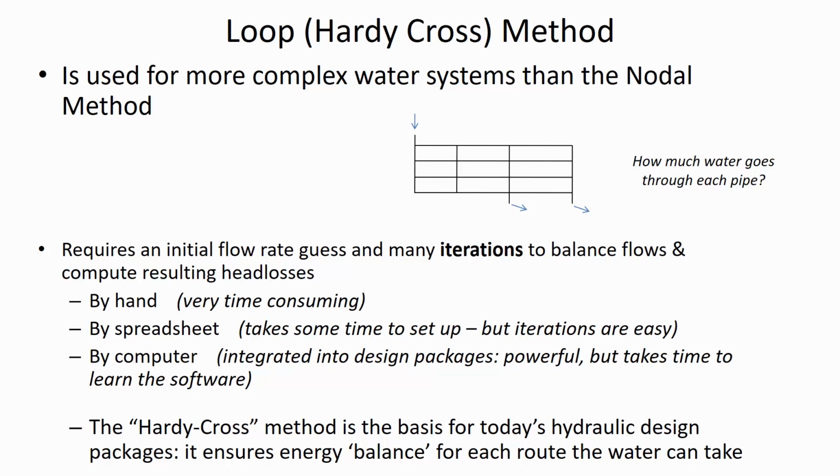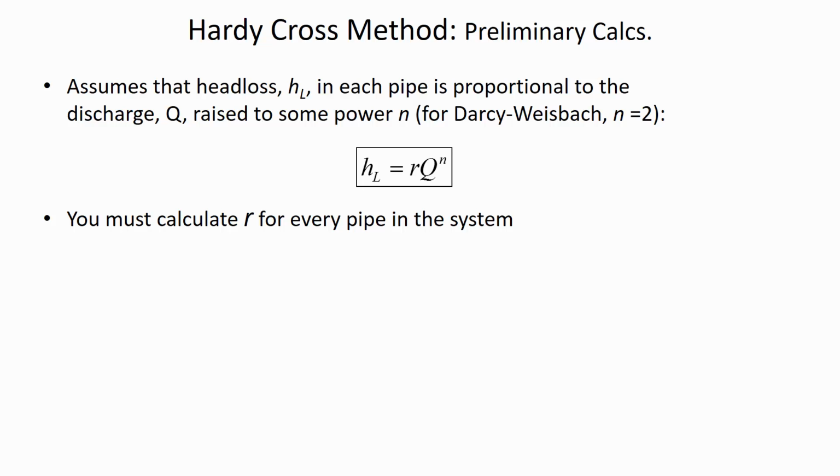You know, if you have a really bad guess of flow rate, then that would throw off your value of f. But for now, let's just say that if we have a reasonable estimation of f, let's say maybe we applied the fully turbulent flow assumption, then in that case, f would be constant. Because remember, the fully turbulent flow assumption just says it's only the relative roughness that dictates the f value. It's not some increase in a Reynolds number. All right. So we're just substituting R into the Darcy-Weisbach equation.